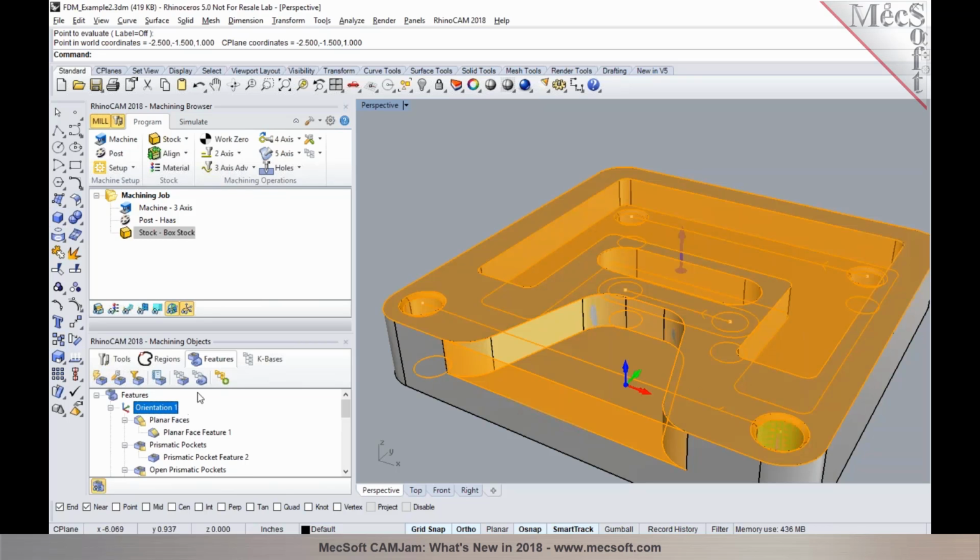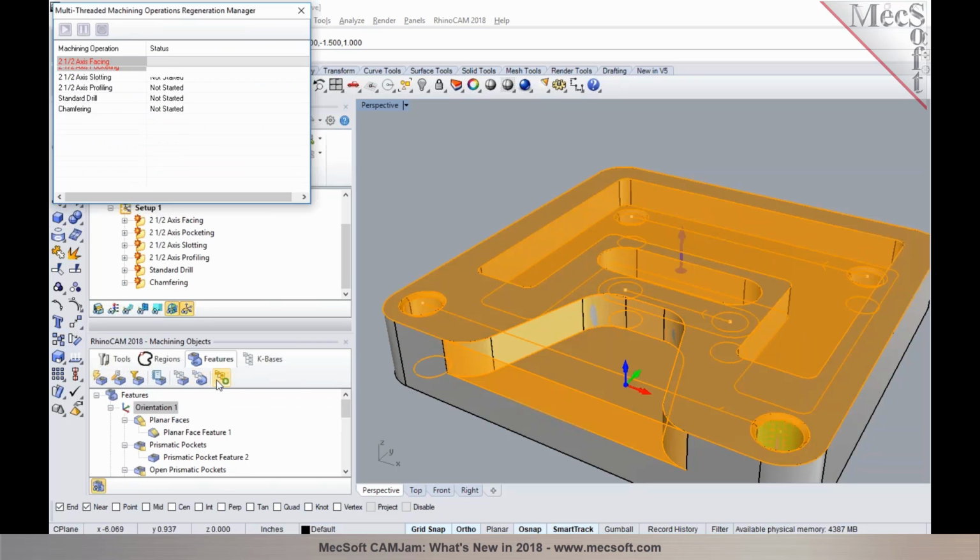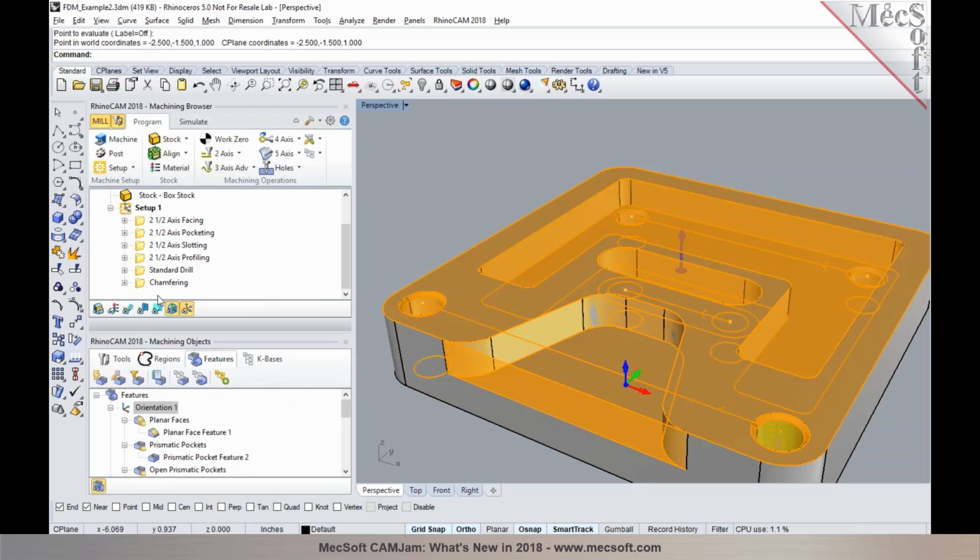So you just highlight the orientation and then click on automatic feature machining, and you'll notice that in just a single button click, you're able to program each of these features in here. You have your drill, pocket operations, slot, facing, all of the operations are automatically programmed with a single button click. Now I'm also going to go ahead and show this to you in our VisualCAD CAM product as well. We'll take a look at another example and see how we can identify some of the other feature types as well.